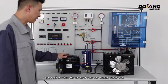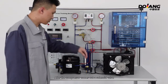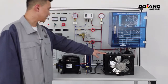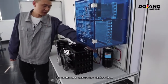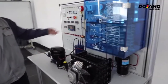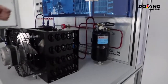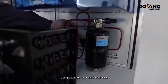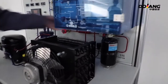Now I will introduce the names of these components one by one. This is compressor. After the compressor comes out the solenoid valve. This is condenser. After the condenser, it goes through a flow sensor. The parameters it measured are displayed here. This is a liquid storage tank. Going down further is a solenoid valve. The solenoid valve plays a role of on-off of the circuit.